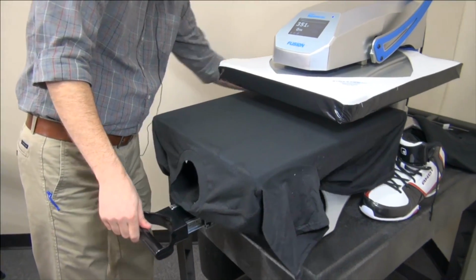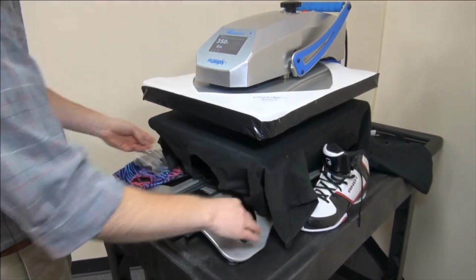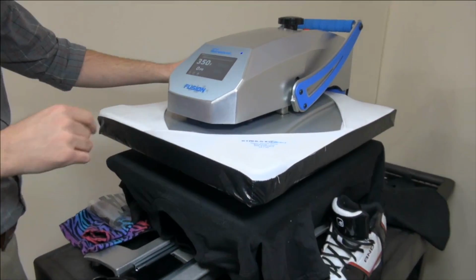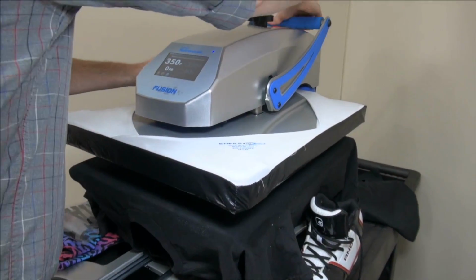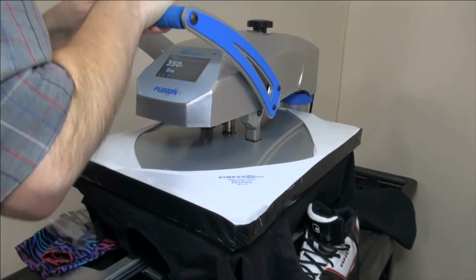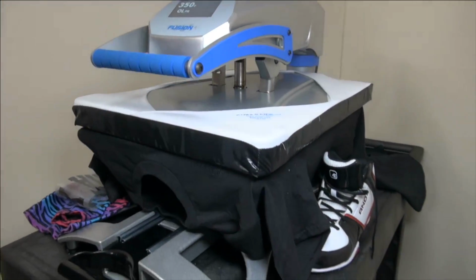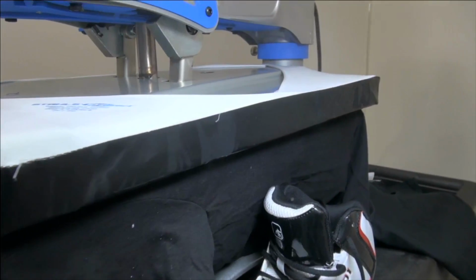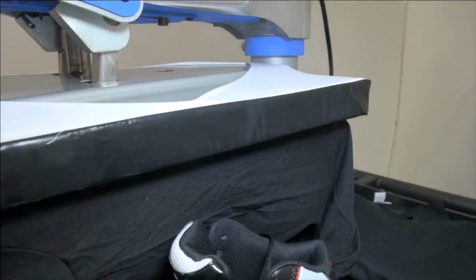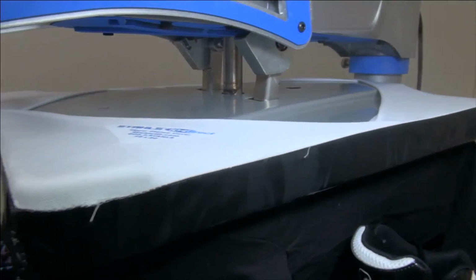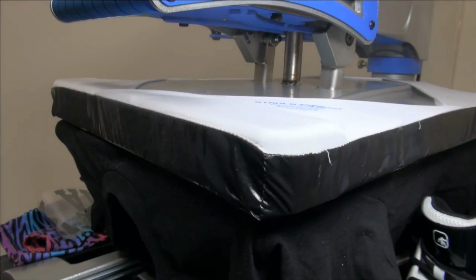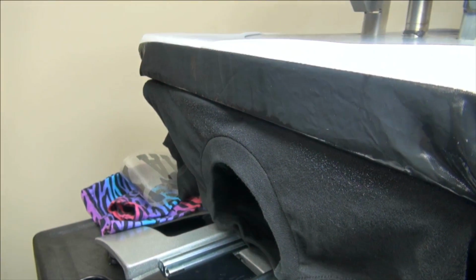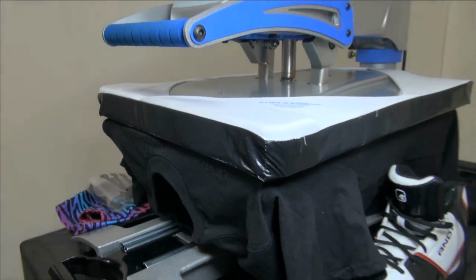Now the pre-treatment solution that I'm using today requires about 60 seconds of cure time at the highest pressure that my heat press can achieve. What that does is it mats down the fibers in the shirt, and it also dries out the pre-treatment fluid. So this is going to be locked down for 60 seconds at 350 degrees. While we wait on that, Jody, do we have any questions coming through that we need to answer? No questions yet. Okay, great. If you have any questions, feel free to add those in the chat window, and Jody can interrupt me, or we'll take periodic breaks to answer those.